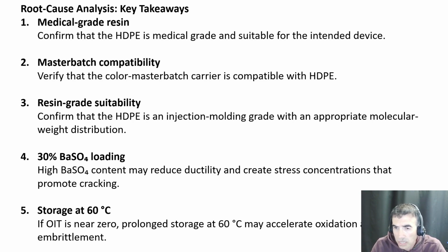And that's a question that we are always dealing with in accelerated aging: would storage at 60 degrees C impact the polymers or not? So a test like oxidation induction time could determine how vulnerable the material is to oxidation.